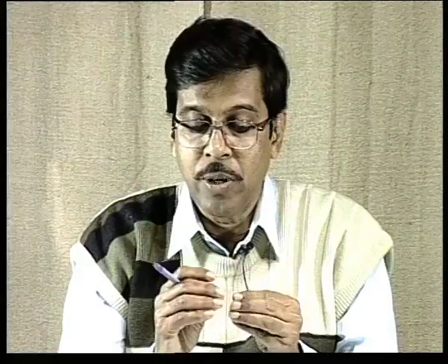I told you again categorically, I earlier also told that whenever there is a change of state, there is an entropy change. That means that change is possible by a reversible process only by heat transfer. You understand? If you consider a process where the change of state is possible with no heat transfer in a reversible process, then only entropy will remain constant. That is an isentropic process.